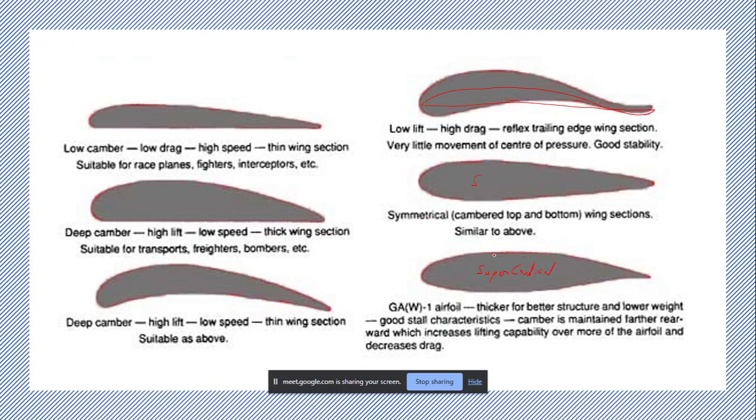Drag divergence Mach number. You're right. Drag divergence delays the flow separation. So the shock wave, instead of forming here, forms somewhere aft. So the shock wave forms here. This is why we came up with the supercritical airfoil.